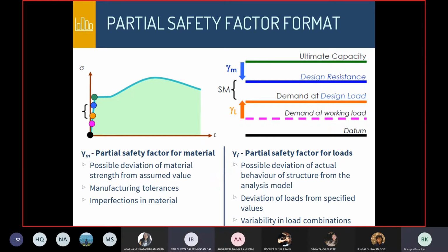Okay. So the way we are trying to understand this is by looking at the stress strain curve of steel. We've said that green is the maximum stress that we can allow to be developed in the material. Any stress above green, we'll say that it has theoretically failed. Now, when we say that it has failed, it does not mean that after we reach a point green, the structure is just going to collapse. That's not how the notion of safety works. What it means is now theoretically we cannot rely on that material to take any more stress. So it has failed.